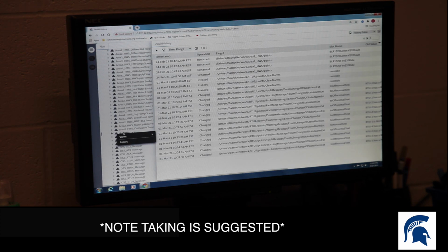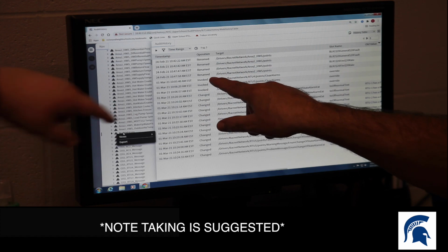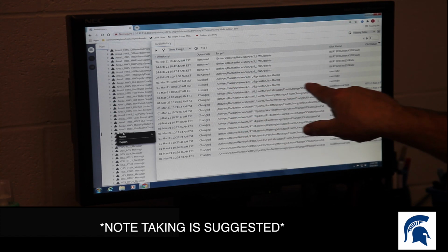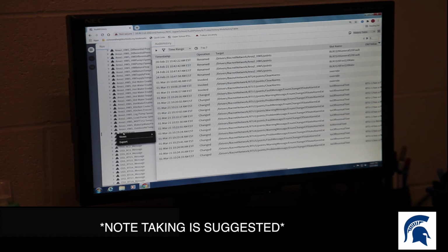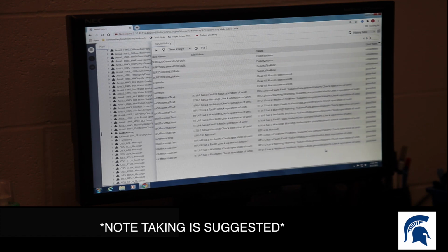Over there, you see those 3 points right there in the middle-ish of the screen? Down a little, yep. If you follow those over, RTU1, you see Override. Somebody overrode the clear alarm point on March 1st. And if you scroll that right-hand window to the right more, with the bar down at the bottom, you can see what value it got overridden to.